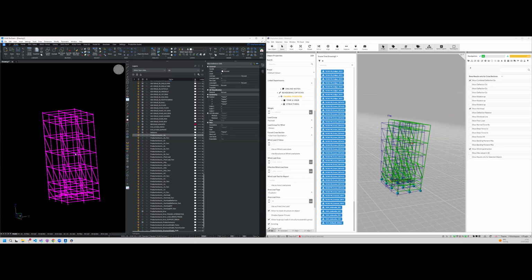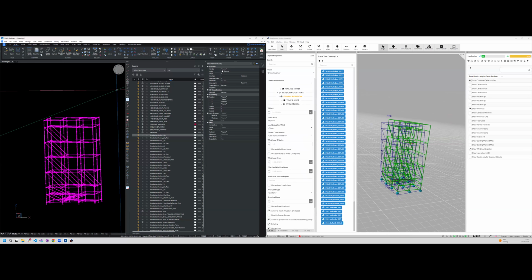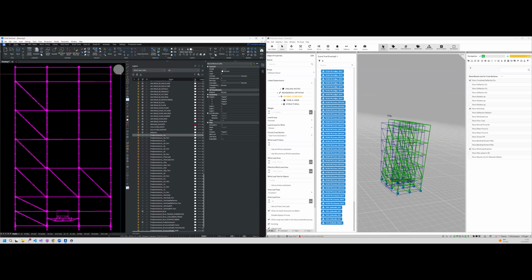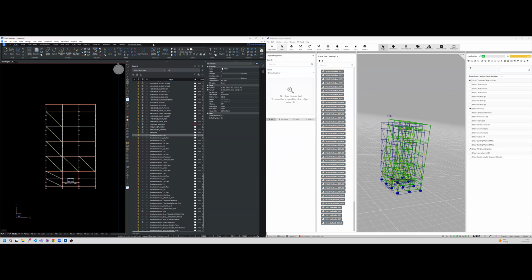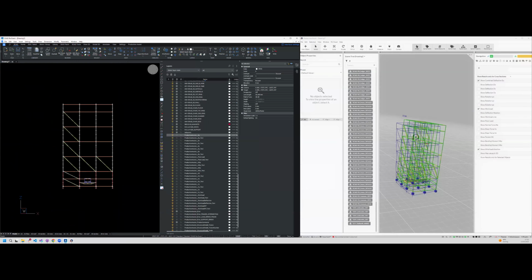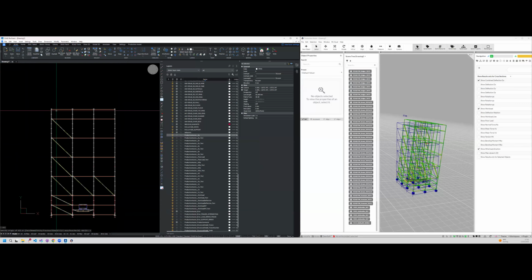But now I want to draw a plane for this. The easiest way to do this is to go into the side view, and in here, click on the button that Bert already showed, which is user coordinate system to view. When I'm doing this, it will automatically align my coordinate system to the view, and I'm able to create a polygon from this.